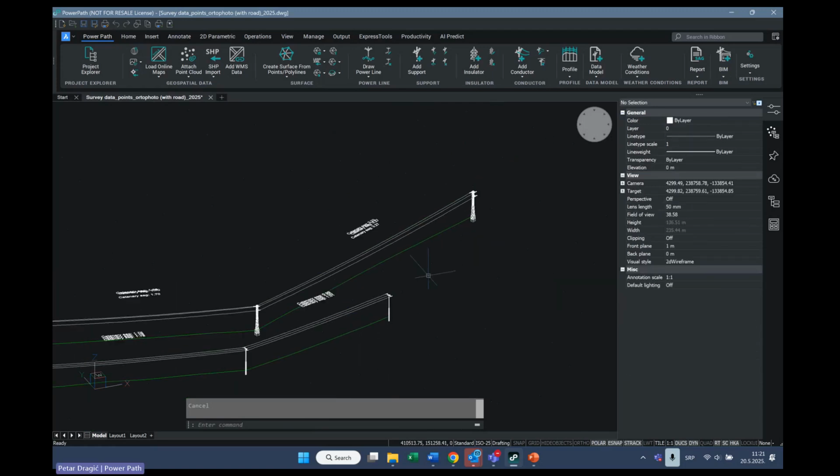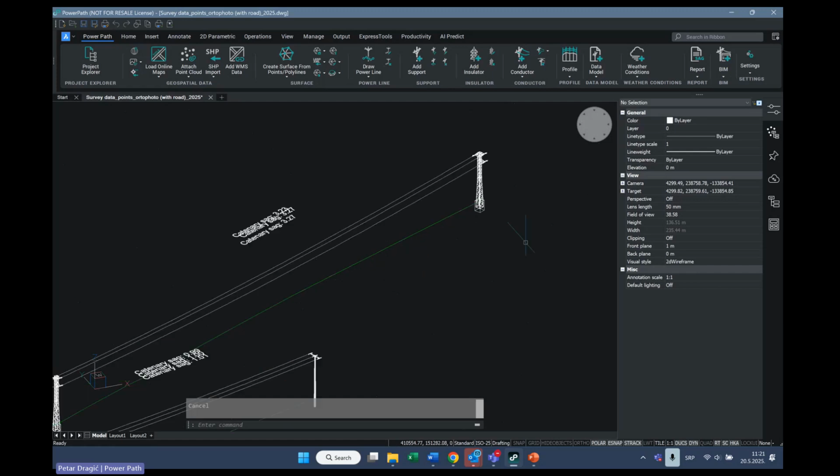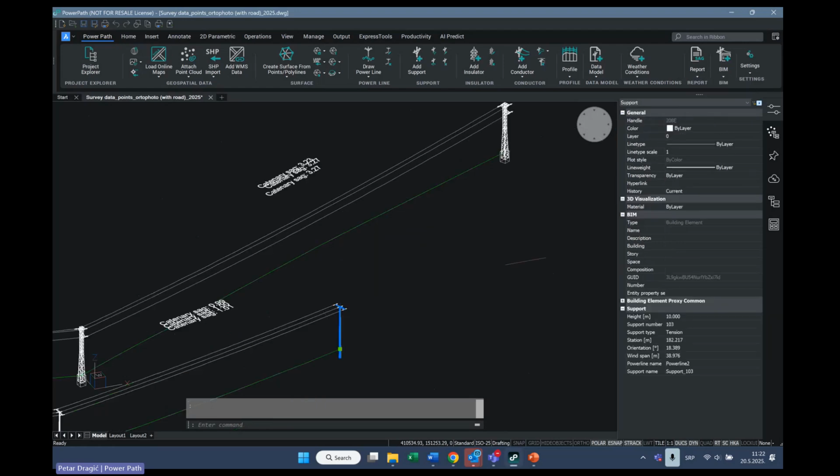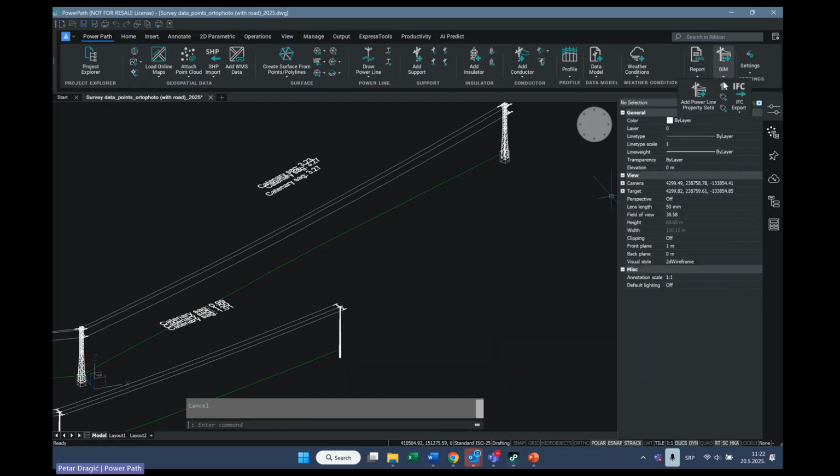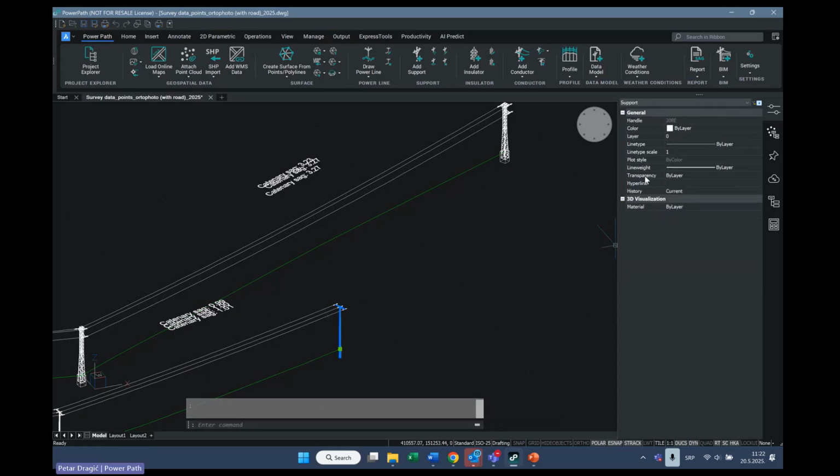Okay. With this command, as you can see, you have full options to control your BIM properties, or better to say property sets. If I go also here on the commands for BIM, there is also an option to classify manually and also to unclassify manually. For example, if you don't want to use our already predefined property set and classification, you can choose the command unclassify manually, select entity and press enter. And if you select that pole, you will see that it is without the property sets.